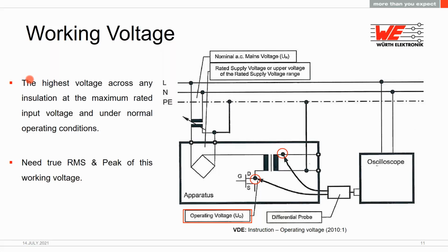In the end, the measured value that you see in your physical power supply can possibly be reduced by maybe adjusting the turns ratio to reduce the reflected voltage onto the primary, of course, maybe a reduction in leakage inductance, or even by applying a harder snubber circuit. The important point is if the measured working voltage is less than the highest rated mains input voltage, we must use the mains input voltage as our working voltage.